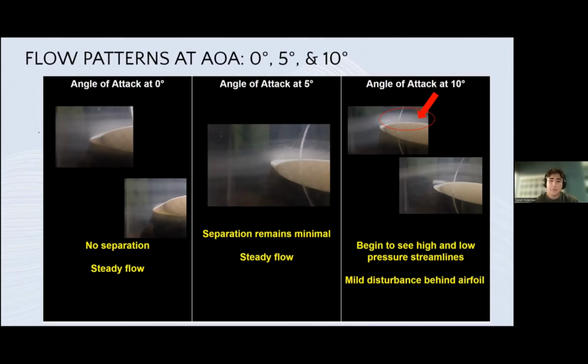At 10 degrees, more prominent effects can be seen on the airfoil. There are significant curves on the streamlines, and the streamlines on the upper surface are tighter and closer together than the bottom. Lift is substantially higher, but drag forces increase as well, leading to localized separation at the trailing edge. These results confirm the expected behavior of the airfoil and agree with our proposition.